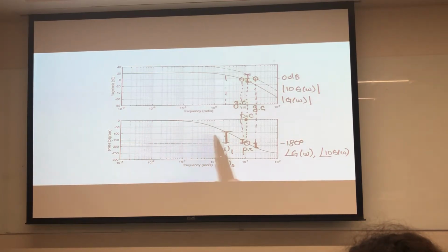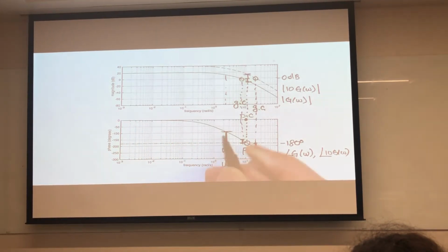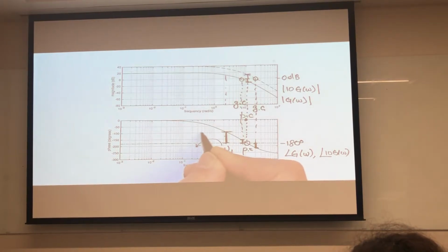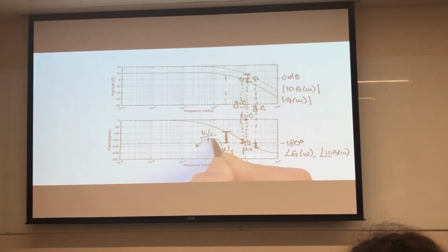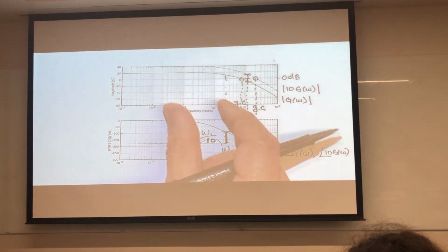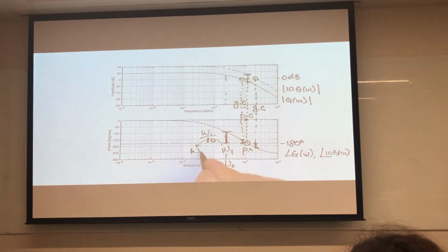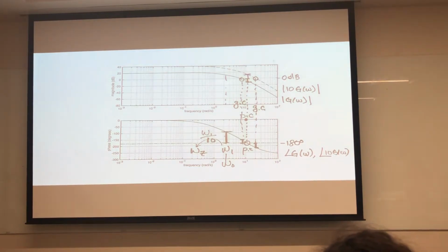I don't want it to reshape the curve while I'm making a measurement right here, so the idea is let's put the lag way over here. So you just take this number and divide by a factor of 10. That's 1 decade. And right now on my scale, 1 decade is about this much. So that puts omega z right here.